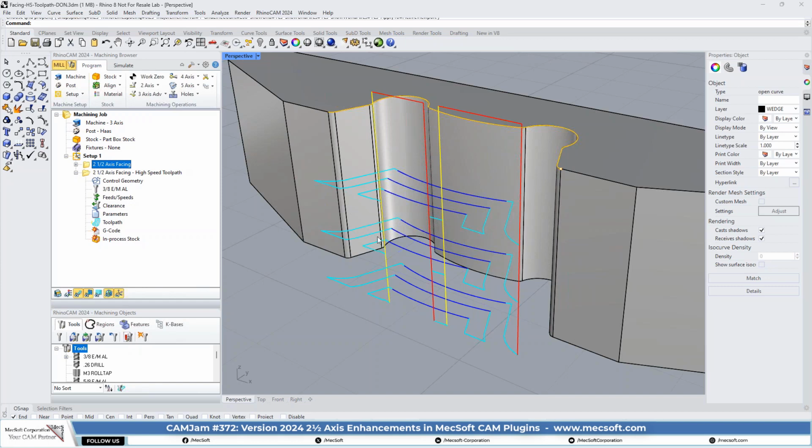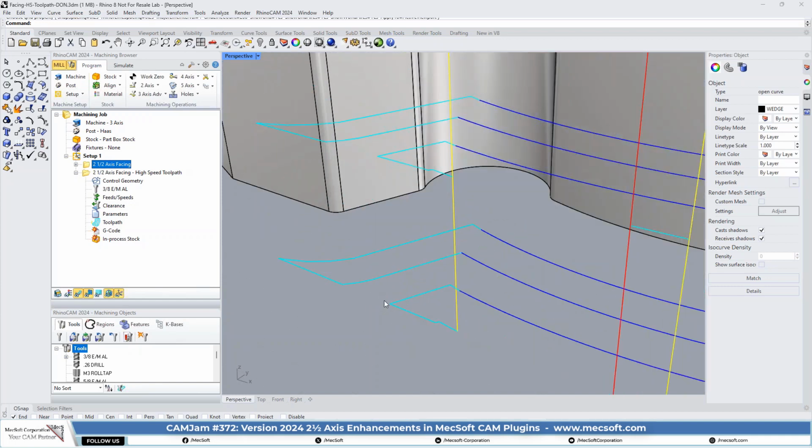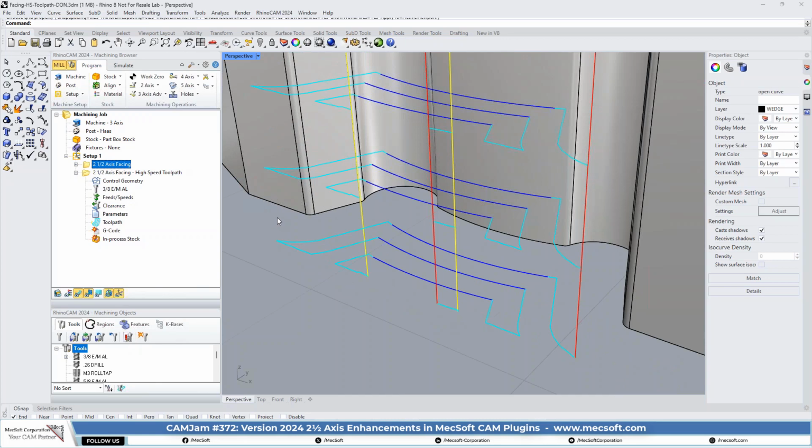It wasn't applied to the entrance or the exit or the movement of the tool to another offset position. You would get a sharp area in here, which is hard on the tool and hard on your machine. In some cases, if you have a lighter router, you would actually feel that jerking motion as that tool goes around that sharp corner.